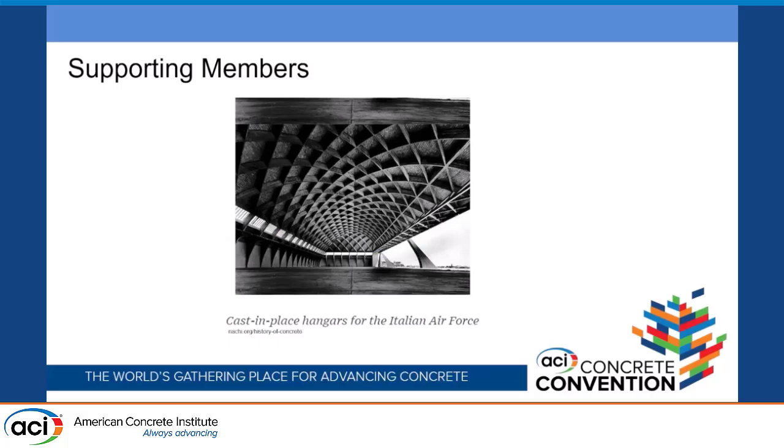So as we're analyzing our shell, we want to look at the supporting members. Okay? They have a huge effect on how our shell reacts. So if we look at this, right here on the back side of this shell, you've got lots of supports. And so this is a very stiff side over here. Your shell's coming in. But on the front, this is a hanger, so you've got really long spans here. This portion of the shell, this edge member, is going to be very flexible, just based on the span and everything. So knowing that, you have to include that in your analysis of your shell, or it's not going to behave like you think it is.